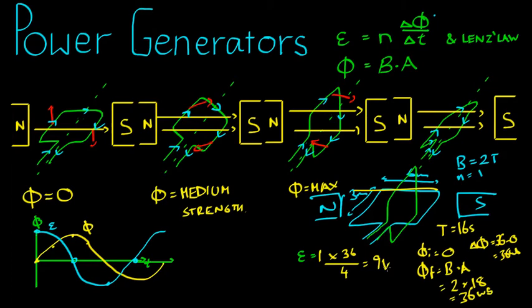It's actually quite difficult. This is a huge loop, you can see, 6 meters times 3 meters. It's quite difficult to get a loop big enough to produce even a negligible amount of voltage. The easy solution, therefore, is to either spin the loop very, very fast and make delta T very small, or to make not a loop between two magnets, but a coil, which means, I'll draw it in yellow, we run a wire around and then keep that wire going around, and finally bring it out, so that we create effectively n number of loops.